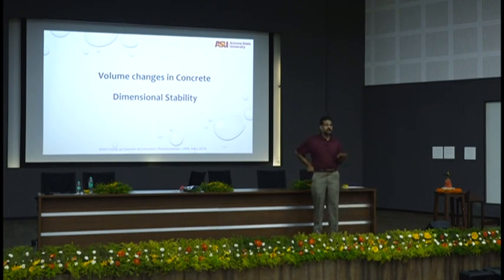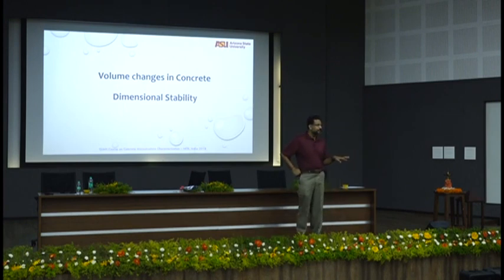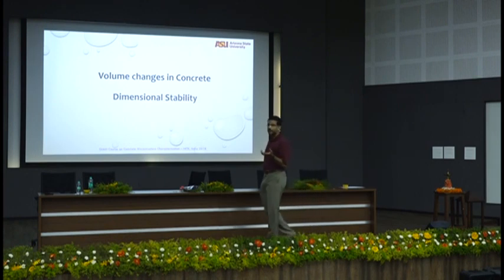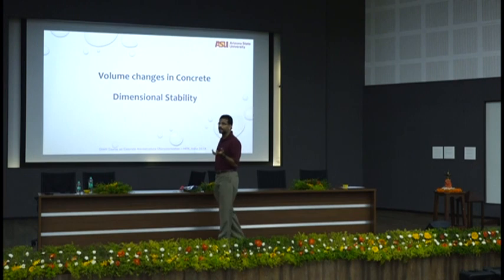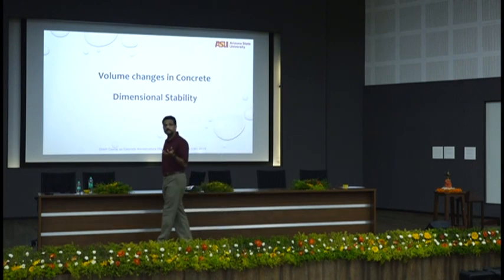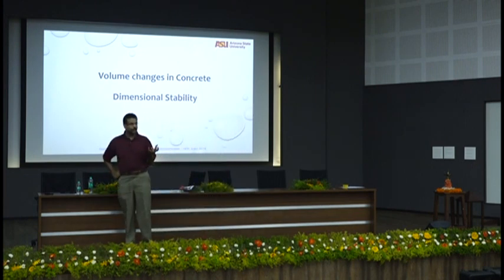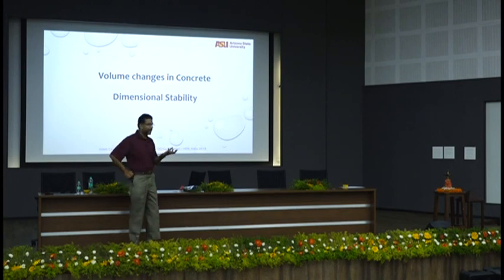Volume changes are part of what you deal with in concrete. There is absolutely no concrete that does not change its volume. I gave you a very simple example. The cement itself, when it hydrates, changes to how many times its volume? Roughly 2 times its volume, right? One grain of cement, when it hydrates, changes to about 2 times its volume. So you have a volume change that already happens.